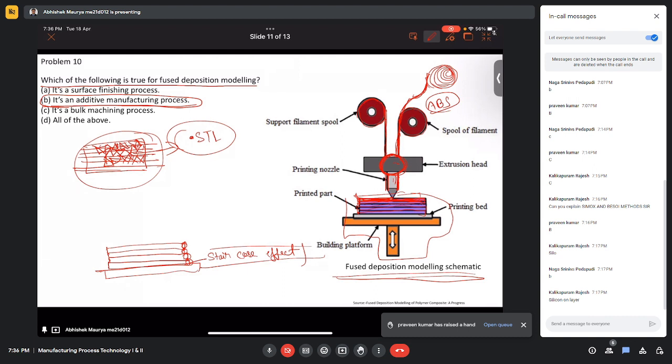But I know the volume removal rate is atomic weight into current divided by valency into density into Faraday. Here the volume removal rate is inversely proportional to density, but in our option, volume removal rate is directly proportional to density of the anode. So it will not be a right answer, right? I think the answer should be A. Wait, let me open that same assignment.